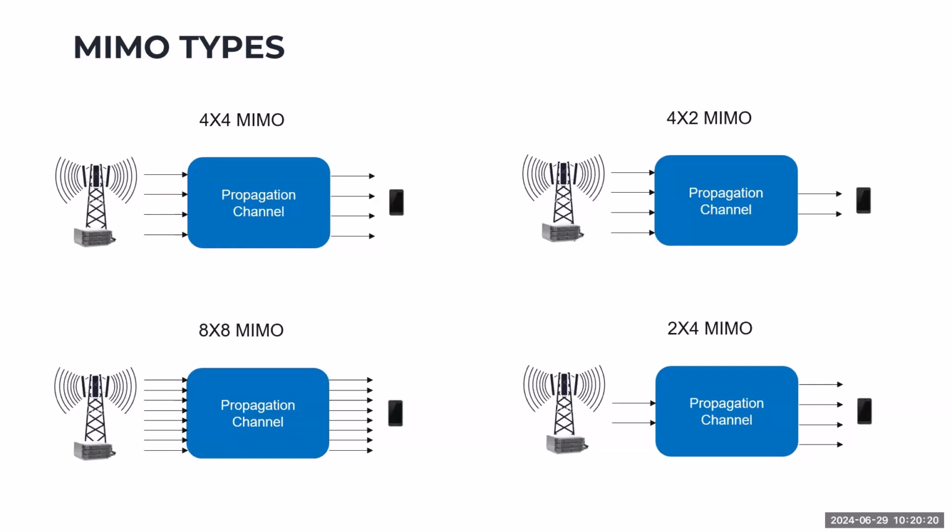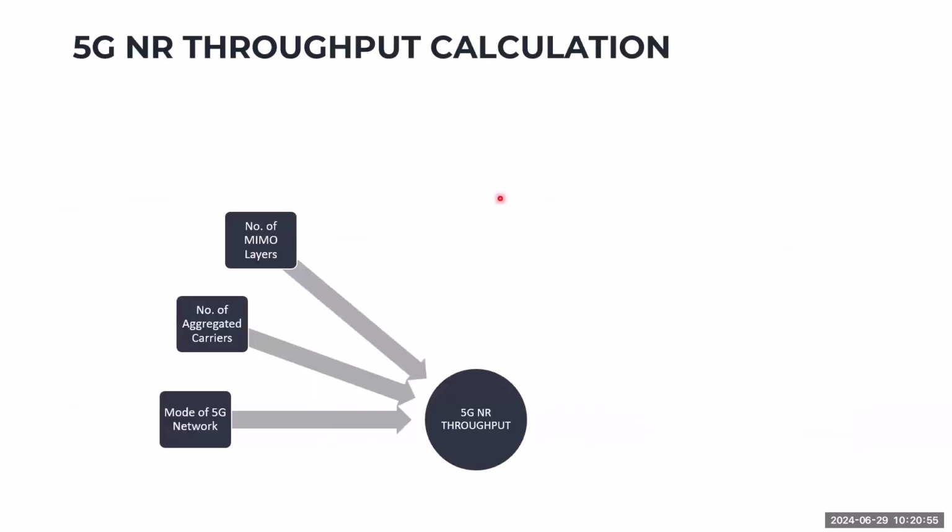So meaning, if we use a certain type of MIMO, like for example 2x2 MIMO, essentially, to make it simpler, we have times 2 of the data throughput that we get because you are transmitting different streams of information multiplied by 2. If you have 4x4 MIMO, it's 4. With 8, you can theoretically get 8 multiplier. So that is the number of MIMO layers.